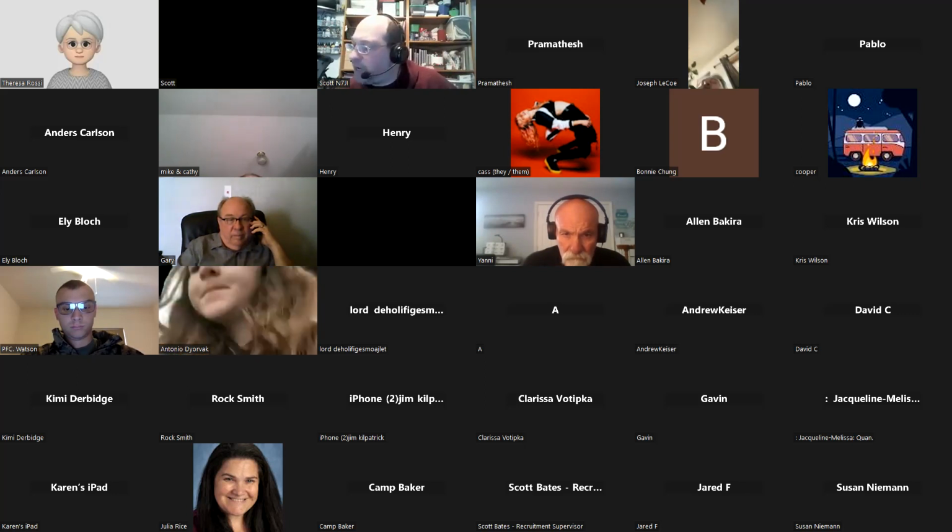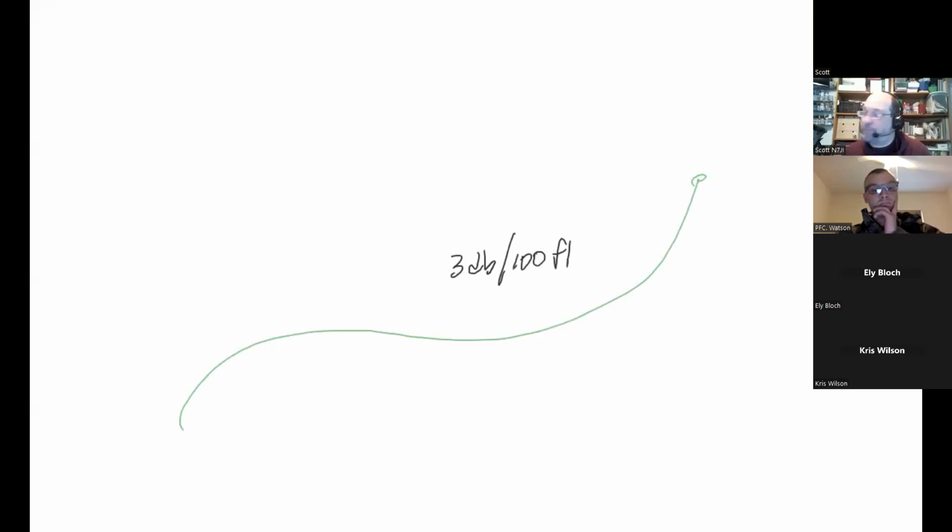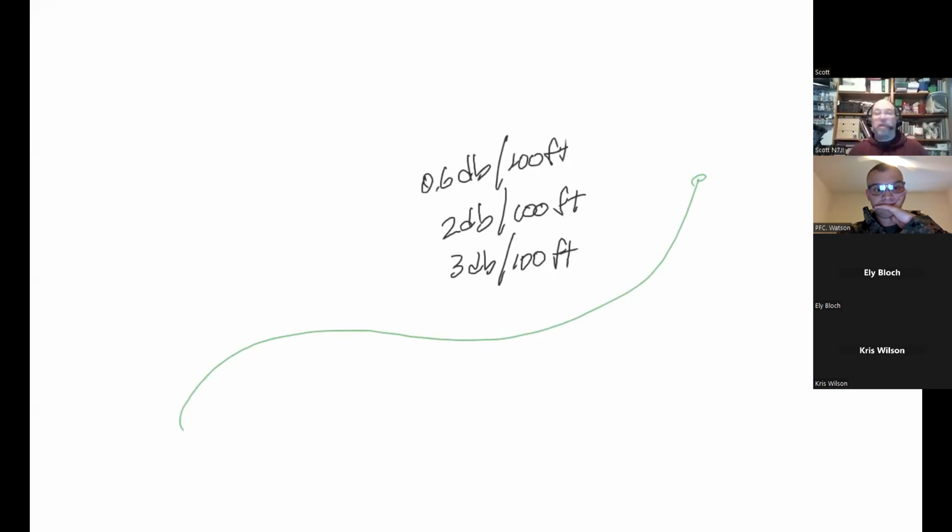If you have, let's say, 100 feet of cable that goes from end to end, its loss is going to be specified as 3 dB per 100 feet, or 2 dB per 100 feet, or really good cable, 0.6 dB per 100 feet. And it's going to be frequency dependent as well. The higher the frequency, the worse the loss becomes. The smaller the cable, the worse the loss becomes.